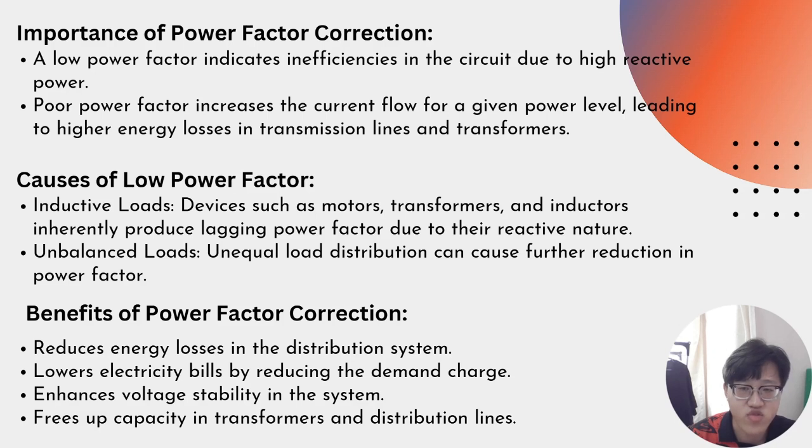The difference between the two loads: inductive loads are devices such as motors, but unbalanced loads are unequal load distribution, which can cause further reduction in the power factor, meaning the unbalanced load in the motor or in the circuit that we construct. Lastly, the benefits of power factor correction are reducing energy losses, lowering electricity bills, enhancing voltage stability in the system, and freeing up capacity in transformers and distribution lines.